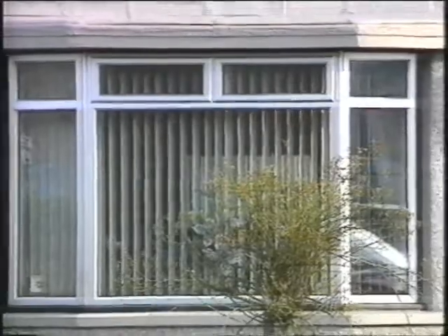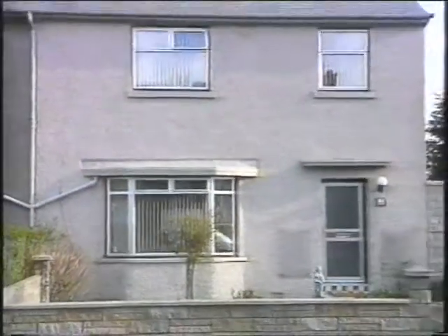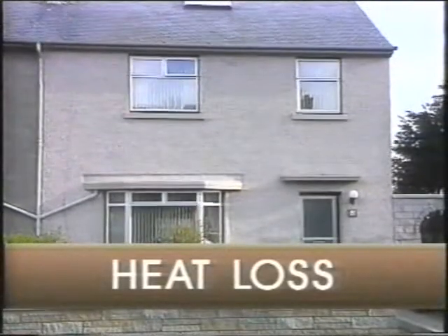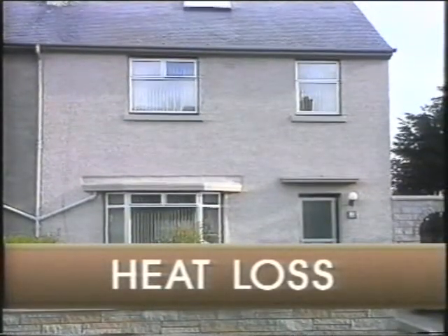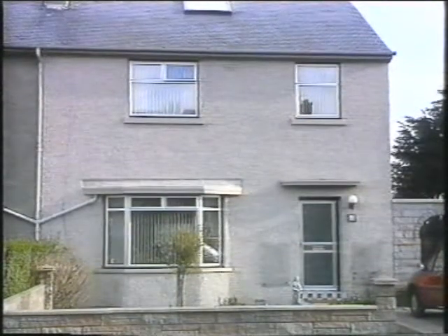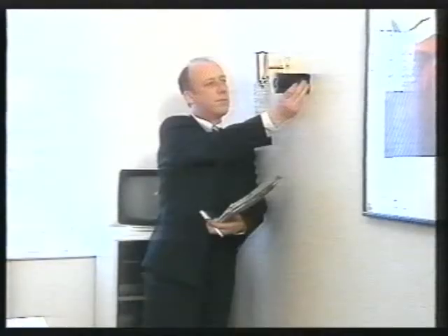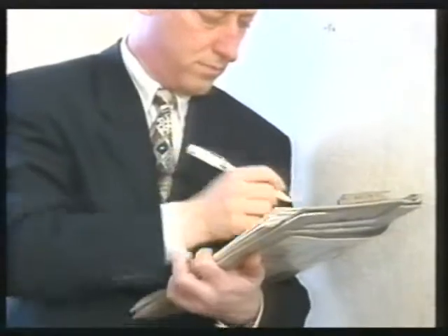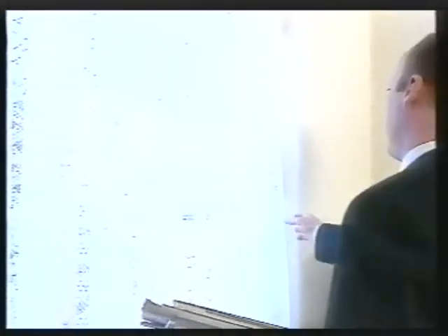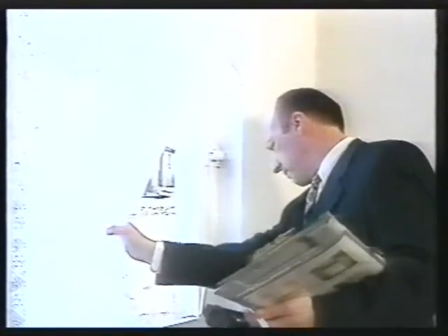The reason we need to heat houses is obvious: for personal comfort and because the heat inside them is continually lost through their fabric and through the effects of ventilation, deliberate and accidental. So to decide how much heat you need to put into a building, you need to be able to calculate the amount it's losing. First of all, fabric loss. That means heat lost through walls, doors, the roof, and so on.